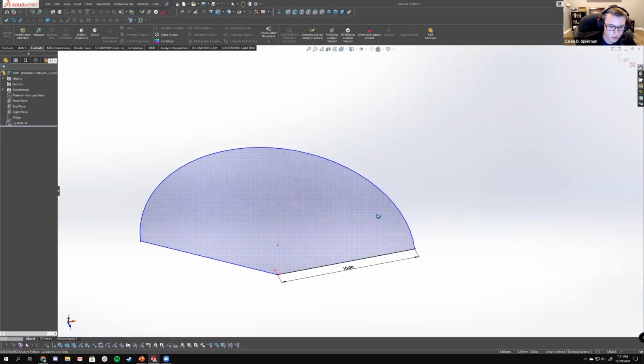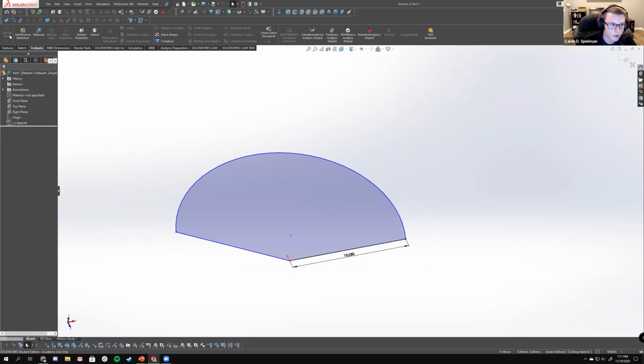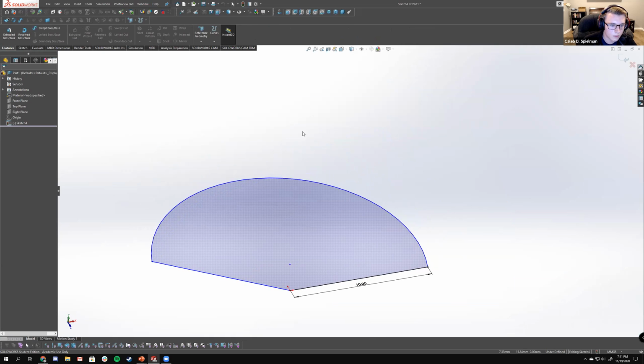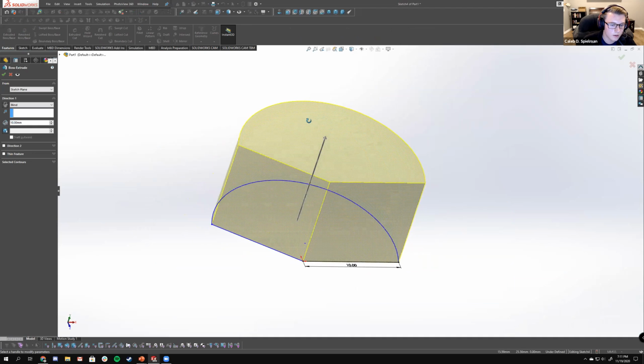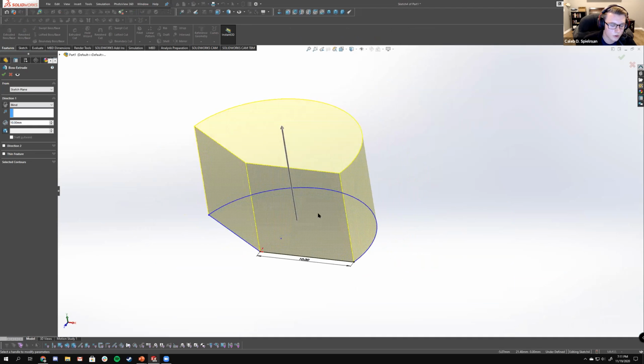So in SolidWorks, after you have your 2D sketch, we have the feature tab right here, and there are many options, but we're going to choose the basic one, which is just extruded boss/base. So we can choose this, and we can begin defining elements of the contour.